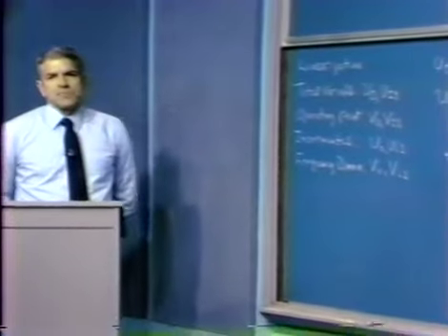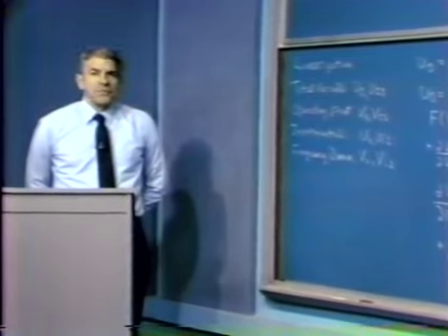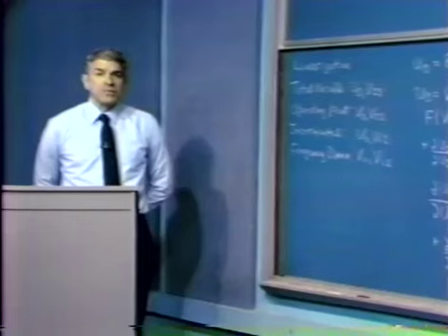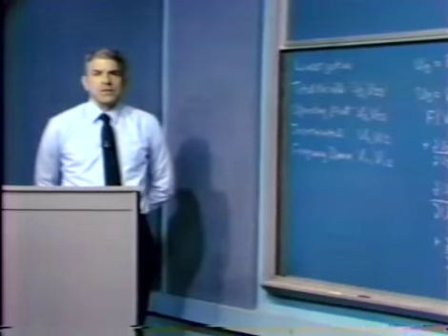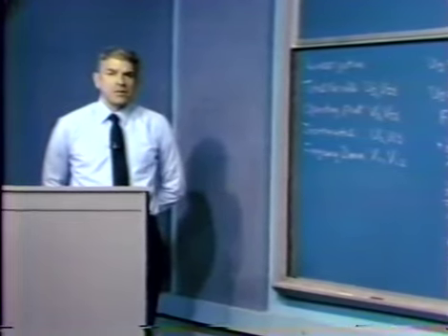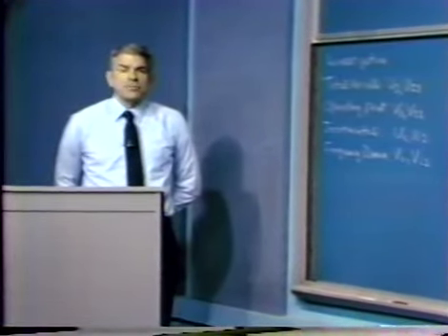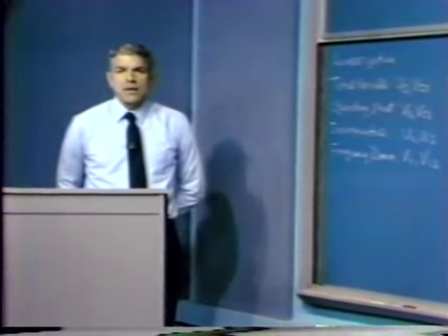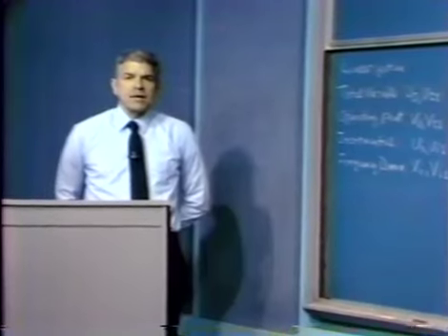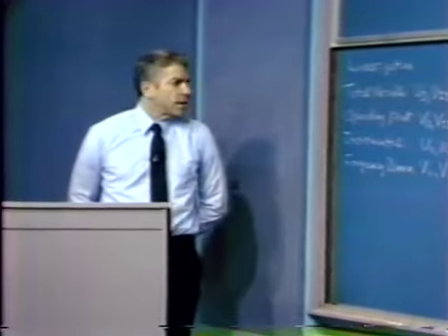I think we've all seen this before in one way or another, since it's a familiar tool to many engineers. For example, the relationship between the collector current of a transistor and its base to emitter voltage is highly nonlinear. Similarly, the various junction capacitances of a transistor are again nonlinear. They're dependent on operating point. And yet we are able to make a linear model for a bipolar transistor and use that to predict the behavior of such a transistor in a variety of circuits. And that technique is, of course, one of linearization, and we'll expand on that idea today.